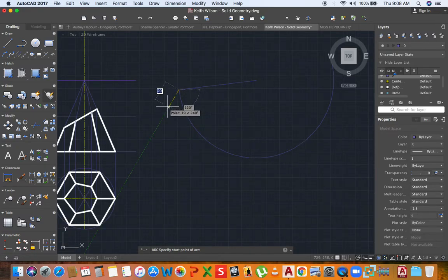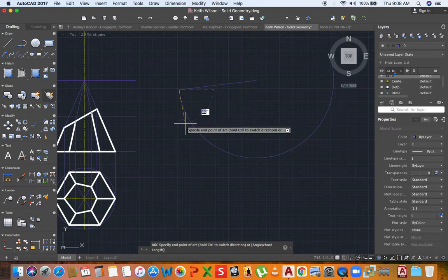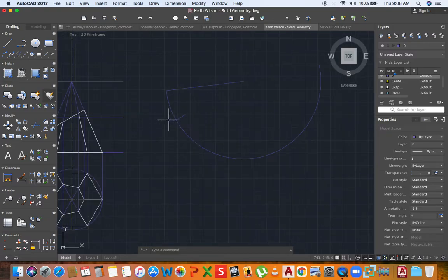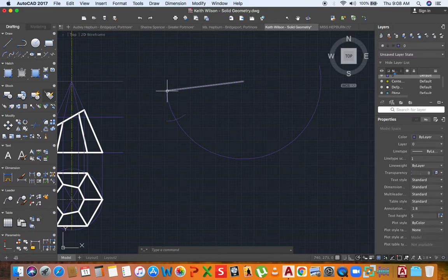It doesn't matter if you pull it here or somewhere to the left. You have to ensure that you type 30 millimeters. Once you press enter, you're swinging the arc. You can click anywhere over this side now. Ensure that you swing it anti-clockwise. So the distance of this arc from this center here is 30 millimeters.